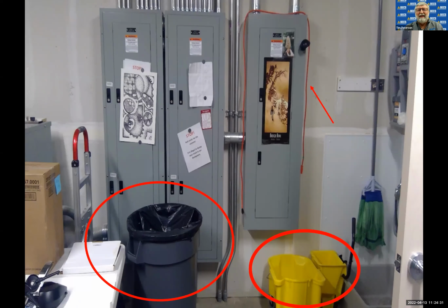I want to stress, yes, they need to have that 3-foot clearance in front of them, but you've got to be able to have access to get to the 3 feet. I was in a facility that had the 3-foot clearance in front of it, but you couldn't get to it because everything was blocked around it. They went, hey, all I had to do is have 3 feet. No, make sure that you can get to what you need to get to in a time of emergency, because what we can never plan on and predict is how we're going to react in that time of emergency. So clear access is very, very, very important.